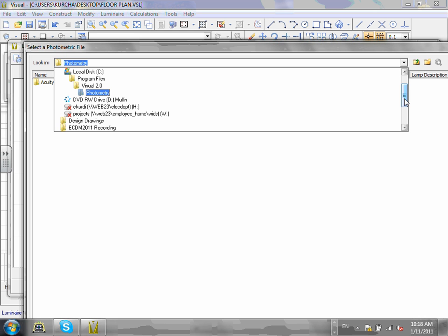Did you default to this? Did you guys default like I did? Yours might be different. Now, Brooks, if you decided to use an LED light, this is where you go to load the IES file. So if you decided to use a different type of fixture, LED light, that's where you're going to load. You're loading an IES file. It comes with a library of IES files that covers every fixture that we need, unless you diverge to a different fixture that they don't manufacture.